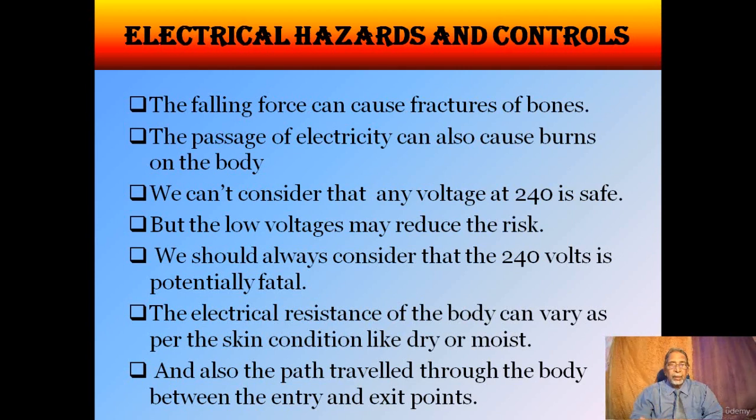We can't consider any voltage such as 240 volts as always safe, but a low voltage may reduce the risk. We should always consider that 240 volts is potentially fatal. The electrical resistance of the body can vary with skin conditions like dry or moist, and it also depends on the path traveled through the body between the entry and exit points.